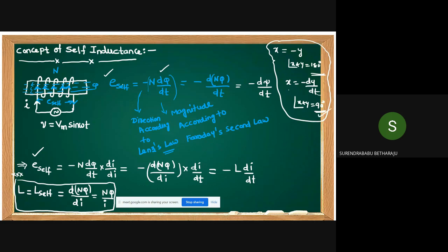That's the reason why, what is the angle between induced EMF and flux? The angle between induced EMF and flux is never 180 degrees. It is 90 degrees. Even for electrical students, with respect to transformers also, once you are drawing the phasor diagram of a transformer, always the angle between flux and the induced EMF, it may be self-induced EMF, it may be mutual induced EMF, the angle is how many degrees? 90 degrees, because this quantity is opposing the rate of change of another quantity.